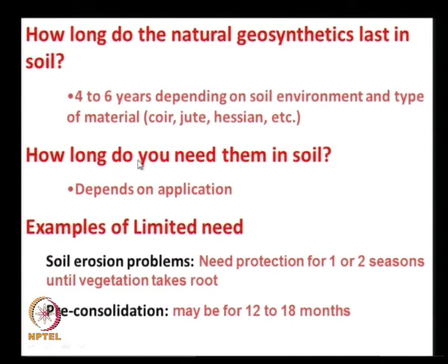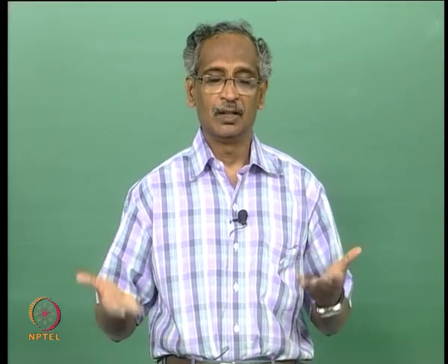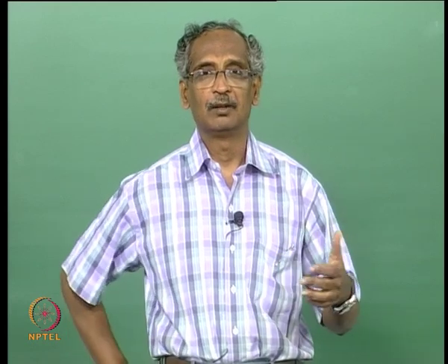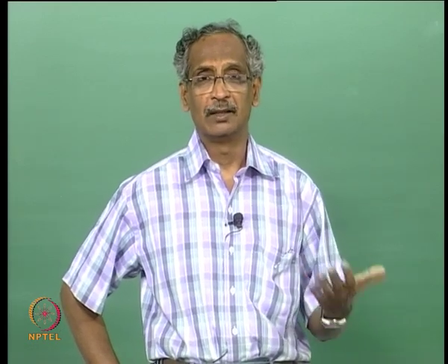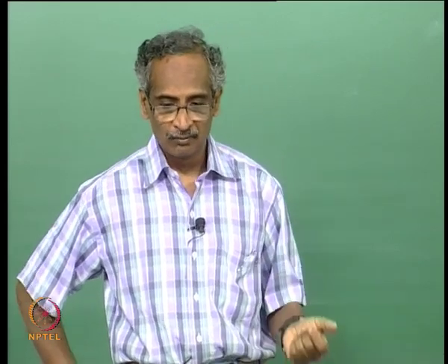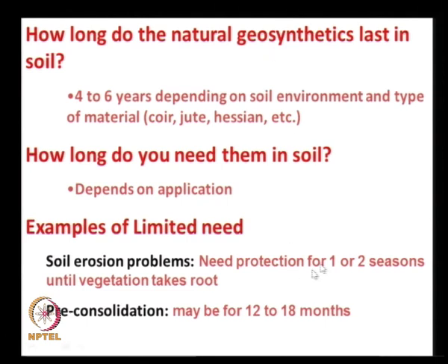And how long do we need the support from geosynthetics that are placed? It depends on the application. So, if it is a below ground application like a ground improvement project, we may require them for about say 1.5 to 2 years until the clay soil consolidates, or if it is a road base, maybe for about 2 or 3 years until the subgrade gains the strength, or in erosion control, we require the protection of the surface only for about 1 or 2 seasons until the vegetation takes root.